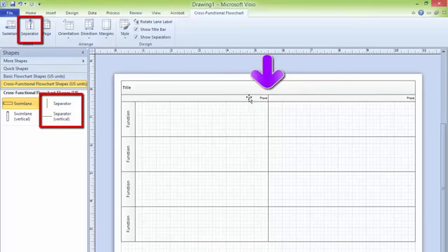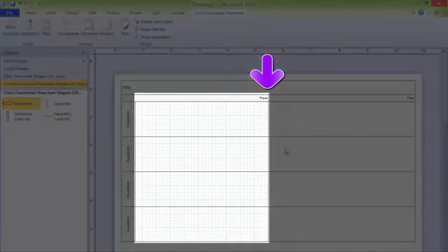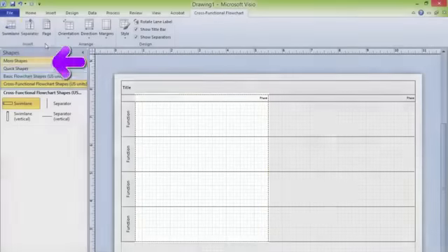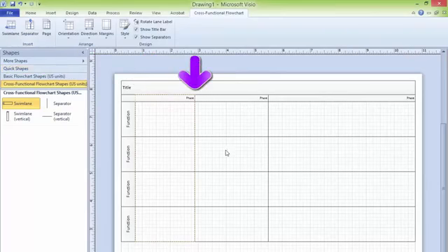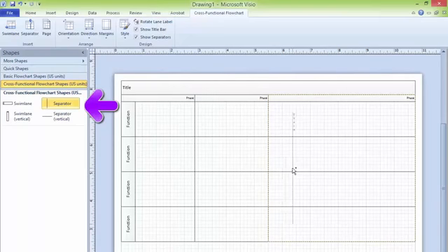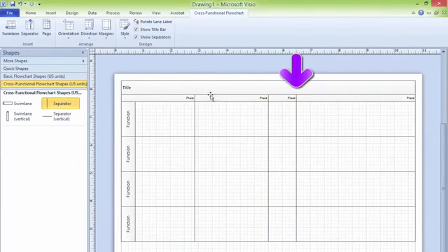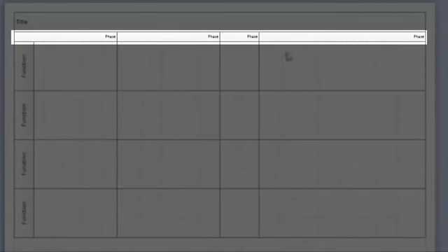Okay, if you are going to divide this portion, then you can click on this phase, and then you can click on separator again. In this way it is going to divide again. Or you can drag from here, and according to your requirement you can place a separator there. You can see that the phases are divided. That means these are different phases now. You can rename these phases like phase 1, phase 2, phase 3, phase 4 in this way.